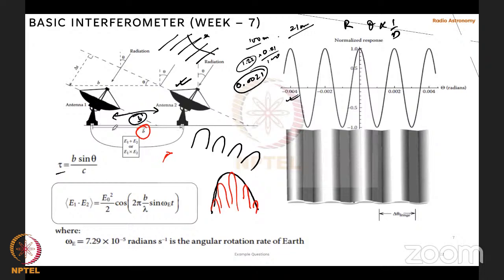And if they are in the same location or the same direction. Say you have a baseline here, and here you have another antenna which is also B. Now if you correlate these two signals, you won't be able to figure out what information it is adding. So in the same line, you can't have a redundant baseline. If you have an antenna here, you can have a baseline here, but although the baseline length will be the same, the baseline vector is different, which will have a different UV coverage in the UV plane.